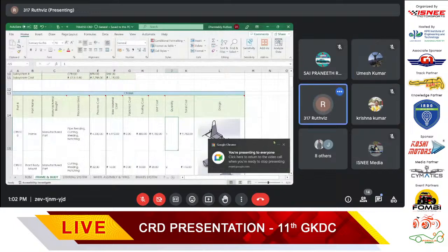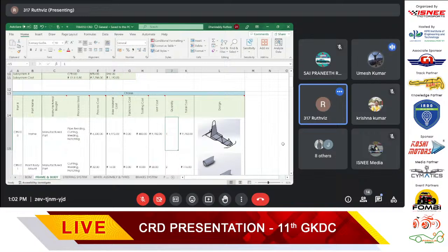Yes, sir. CF 100, sir. So this is a frame part. In the process cost of 4,330 rupees, we have pipe bending of 700 rupees, notching of 456 rupees, cutting and grinding of total 750 rupees, welding of 4,091 rupees. Here the total weld length is 247 inches. Cutting and grinding took us around 150 minutes. The cost of operation is 635 rupees. That's it for the process cost.